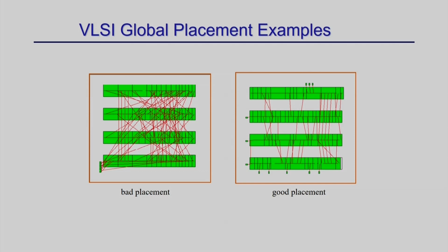Okay. So, here is another example of bad placement. These are all components placed, and this is the interconnection. You can see there are a lot of crossings, right, and here if you just reorganize them, you can have a good placement where the wire length is less. So, placement does this. It makes a good placement so that your total wire length is reduced.